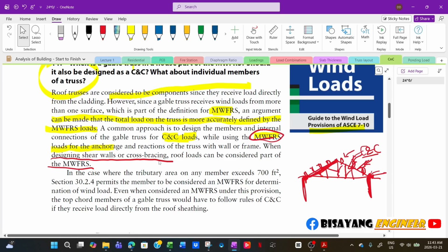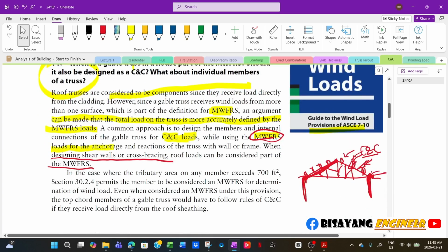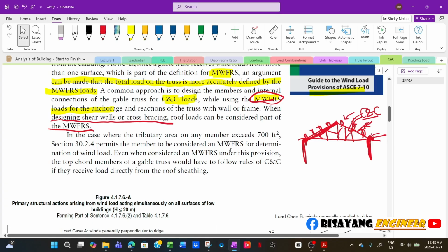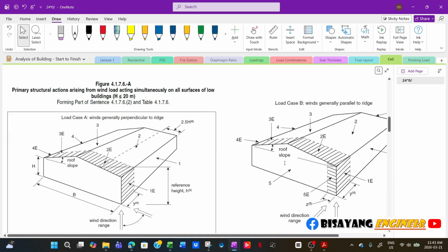Our codes back home in the Philippines use wind load from ASCE 7 anyway, so I would assume the way it is worded in the National Structural Code, the NSCP, would be the same as this one. So again, there is no windward only and leeward only combination in wind loading. It always goes together, like windward plus leeward.